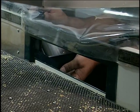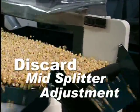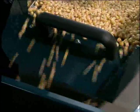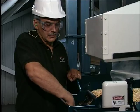minimizing discard rates. If your Pegasus has the optional middling rerun conveyor, then you must monitor the position of the discard and mid splitter. This splitter is located in the middling discharge hopper at the end of the deck. The position of the splitter will determine the proportion of the middling fraction that either goes to discard or is returned to the deck via the rerun conveyor.